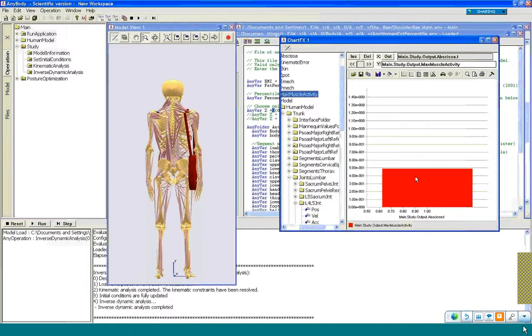Of course, the small female has weaker muscles than the large female had. But the small female also has a smaller body mass to begin with. And also, because of the scaling of the model, the point of application of force from the shoulder bag is actually closer to the center line of the small female than it is to the large female. So you can see that when we do these types of scaling, there are a lot of different factors coming into play. Now, what about the forces in the lumbar spine then?